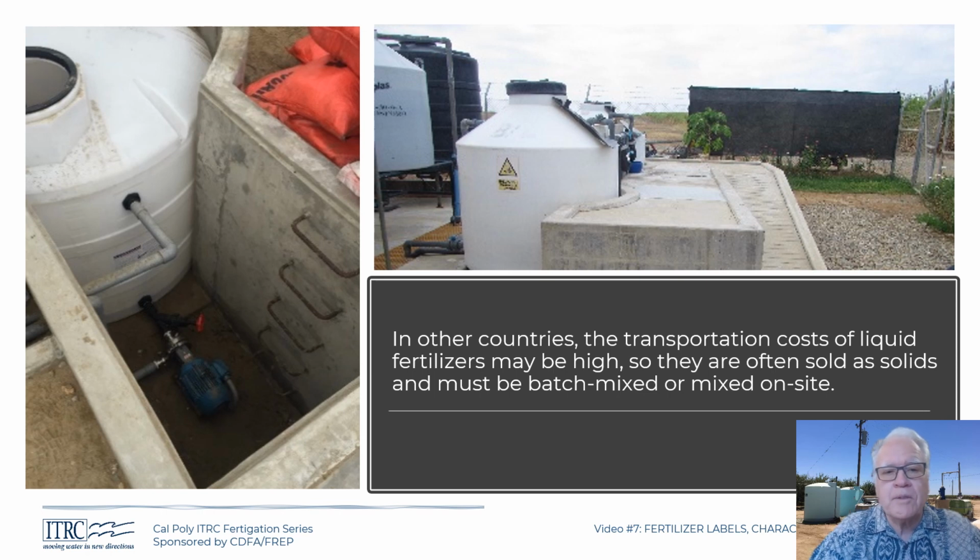And you have two pictures here, one on the left, one kind of on the upper side. The one on the left shows a tank that's easy to fill because the top of the tank is about ground level. And then there's a pump down below. But as you can imagine, whenever there's a leak, this gets kind of gnarly in terms of trying to repair everything. So that's generally not recommended. What you really ought to have is everything above ground, which you sort of see on the right.